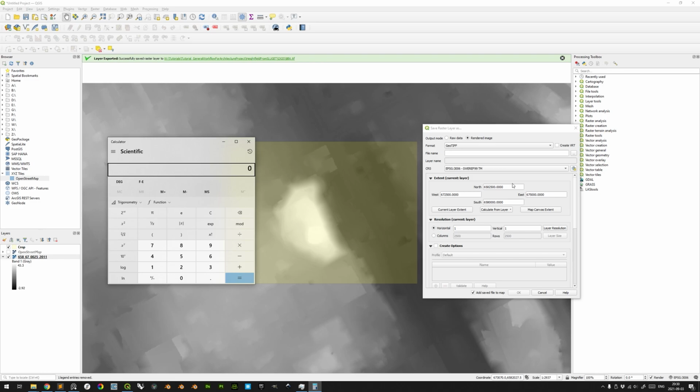This is sufficient thanks to each of these 0 to 255 values being mixed between the 3 channels, in the sense of 256 times 256 times 256, or 256 to the power of 3, producing 16,777,216 unique color values by mixing the values of the red, green, and blue channels. On the other hand, with the single channel 8-bit grayscale image, we are stuck with only 256 values. This would mean that if we have a landscape that is 255 meters high from bottom to top, then the resulting landscape model from such an 8-bit height map could only represent 256 different heights, and as such would produce 1 meter high terraces between each value, similar to what we see here.